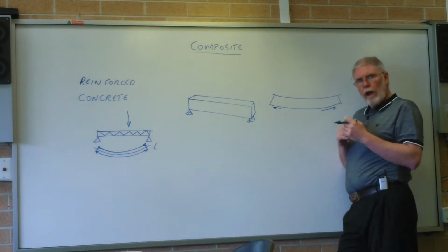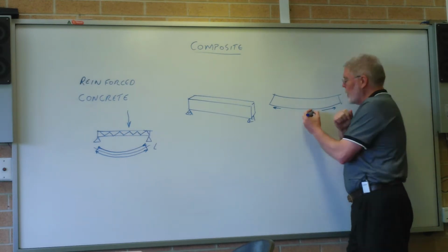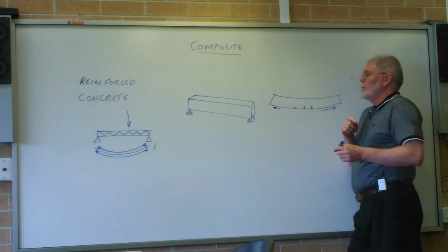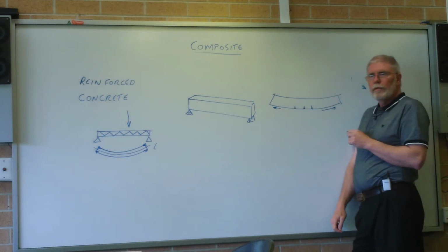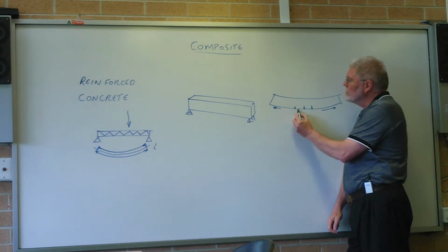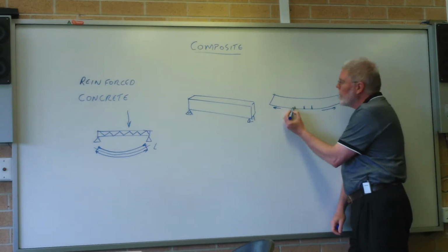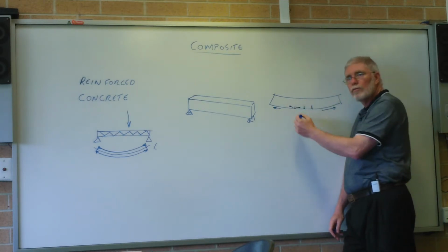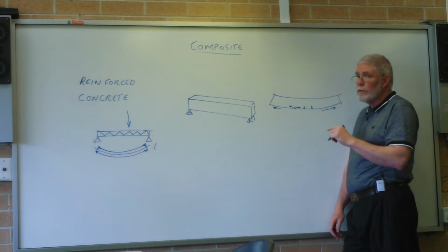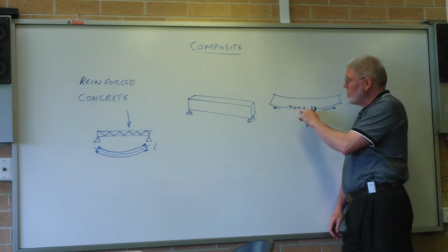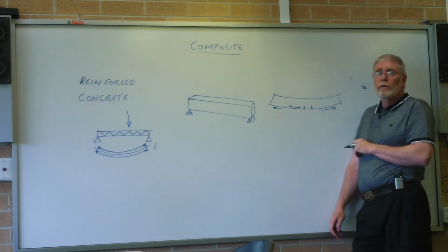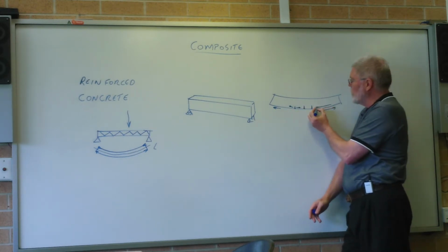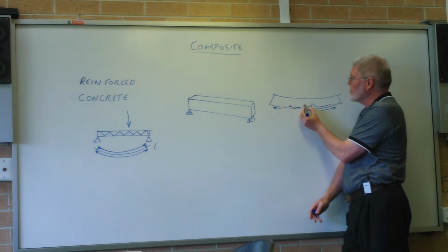So if there's a crack in the surface, that crack, I'm exaggerating them here, becomes a problem for the load because there's no material for the load across. So that material here is being stretched, but there's nothing holding the two together. So that's not where the load is. The load can't be shared across that section because there's a gap there. So what the load has to do is go up and over the cracks.